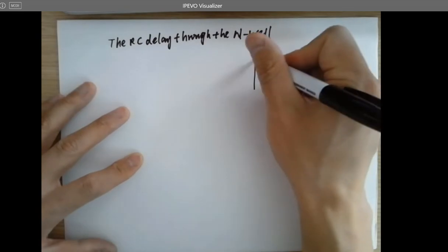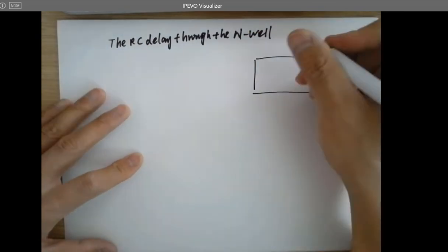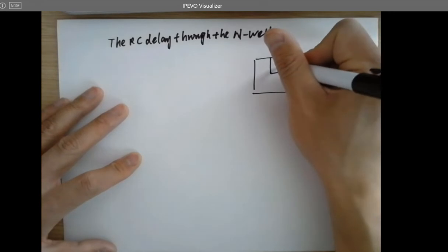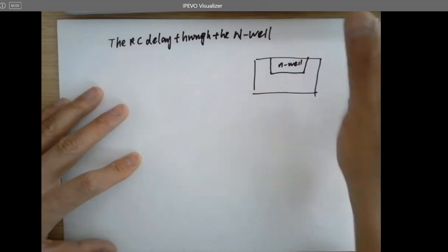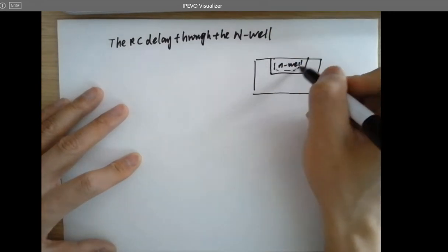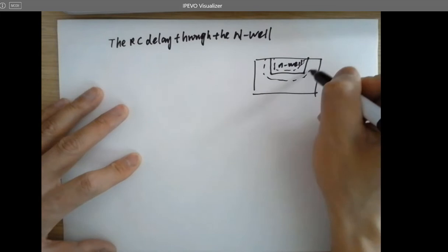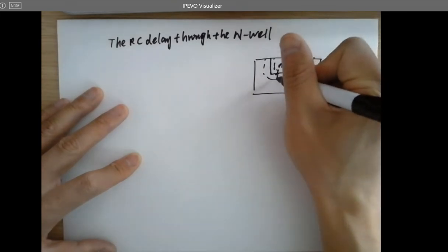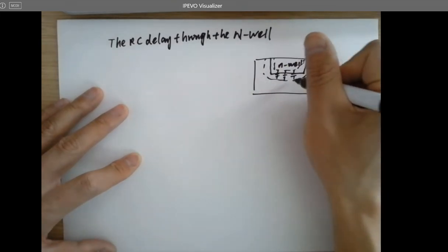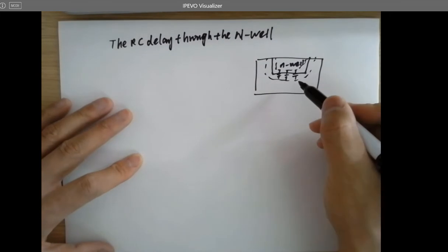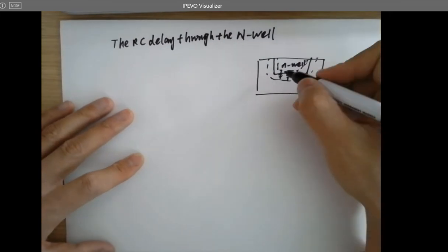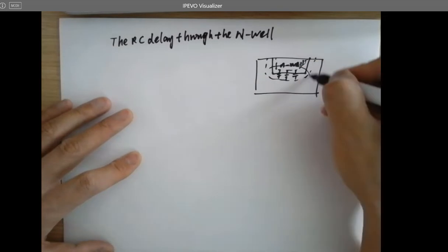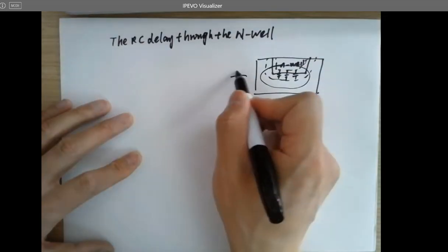And as we know, an N well being doped into the P substrate, and there will be a depletion layer surrounded. So there is parasitic capacitance in between the N well and the P substrate. And because the N well is being used as a resistor, we just model this whole thing here as a circuit like this.